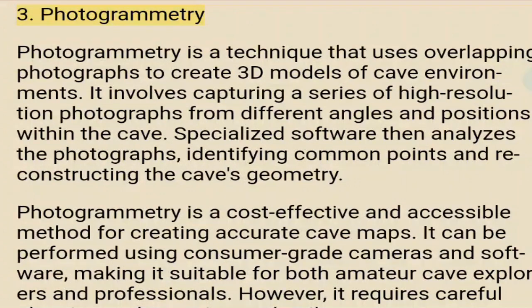3. Photogrammetry. Photogrammetry is a technique that uses overlapping photographs to create 3D models of cave environments. It involves capturing a series of high-resolution photographs from different angles and positions within the cave. Specialized software then analyzes the photographs, identifying common points and reconstructing the cave's geometry.